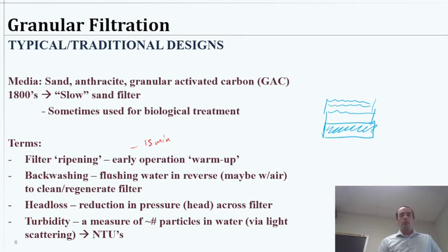Okay, then we have backwashing. Backwashing would be flushing water in reverse. Mentioned it already. Sometimes we use an air purge as well. I'll take us through a couple videos just to experience that virtually in a few minutes. And that's to clean and regenerate the filter. Then we have terms to describe how we know when it's time to backwash. So we have first head loss.